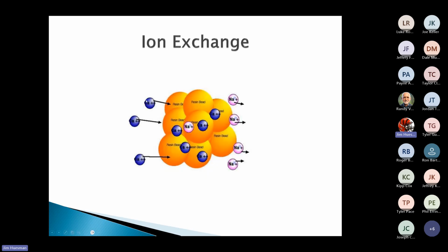So what's happening though is that it comes down and hits, and then it releases, but once we have 2 to 3 calcium or magnesium ions tied to that media, it's dead. It's 100% dead. It's not going to collect any more than it already has on it.